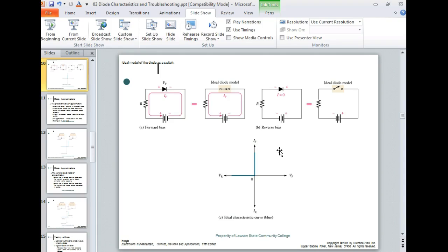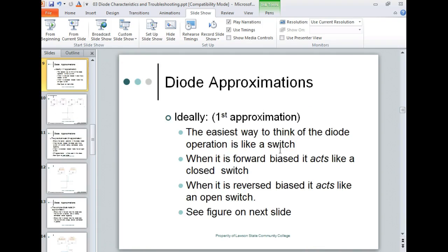And we're going to start off with forward bias of the diode. We're going to start off with 0. We're going to measure across the resistor, and while we're measuring across the resistor, we're going to use it to calculate current. So we're not going to have to use an ammeter. We're going to use the resistor to calculate the current. And we're going to slowly increase the voltage up, and we're going to start getting current flow. And then we're going to create this graph right here.